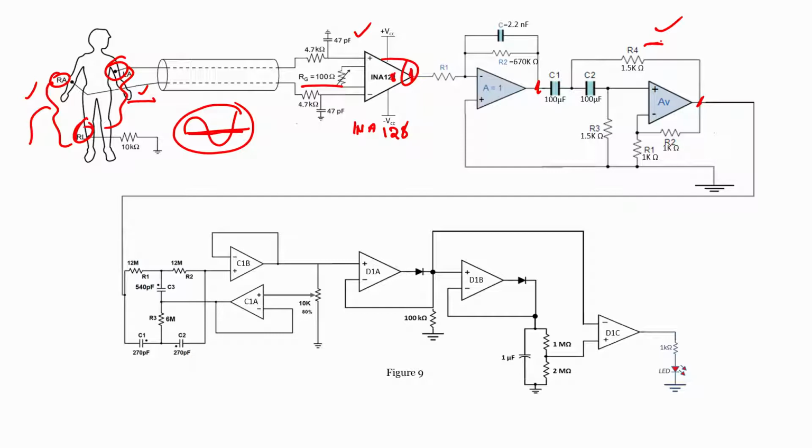Then we also have some odd multiples of our power line interference, which are greater than 100 Hz. By using our low pass filter we are completely eliminating them, and the notch filter removes our 50 Hz signal. We have also seen in a practical, as well as theoretically and in a simulation version, how exactly this works. So we will only show till this point, because this requires some more computational effort in order to do verification.